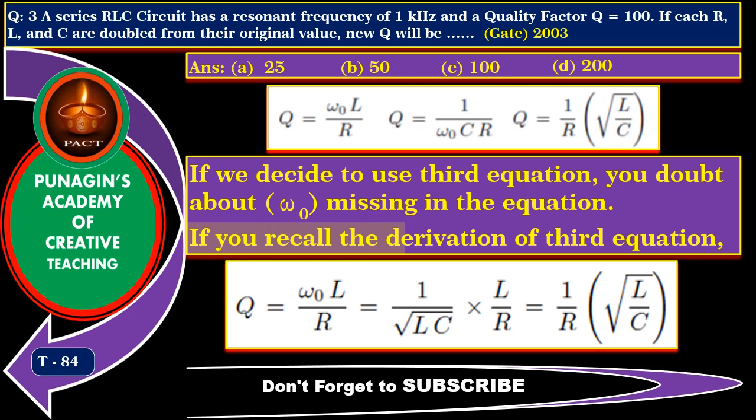If you recall the derivation of third equation, we started with Q is equal to omega naught L by R. By substituting for omega naught equal to 1 divided by root LC, we obtained Q is equal to 1 divided by R into square root of L by C. It means while deriving this equation, we have taken care of omega naught.